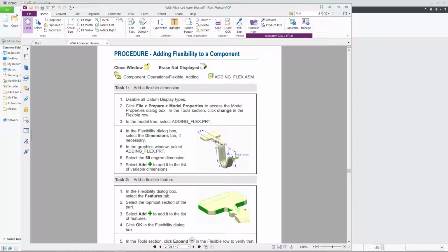And then when this component gets assembled, the intention in this case would be that this component is made out of brass, and it will be pushed down into a plastic housing and then clip in place, and then the tab that was used to help the user handle the component is then twisted off. So the tab is removed in the final assembly state of this component.